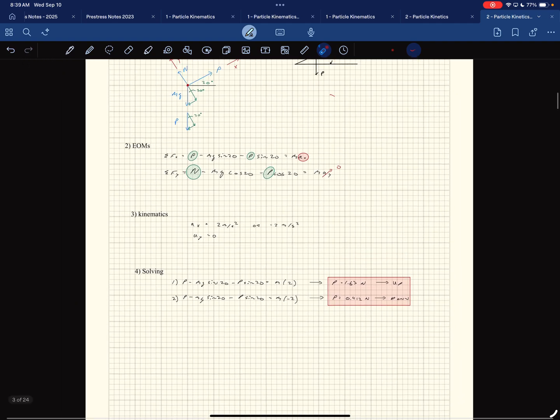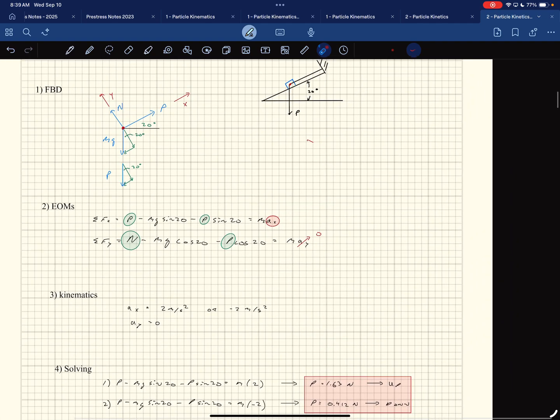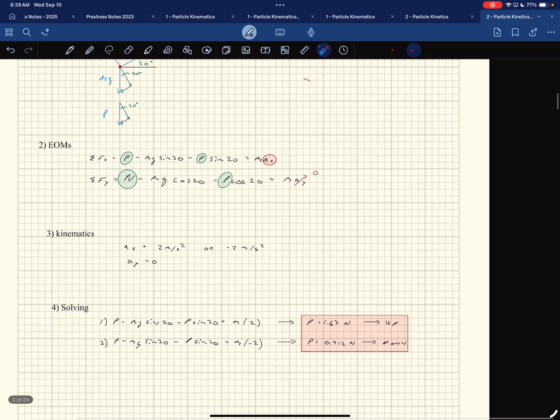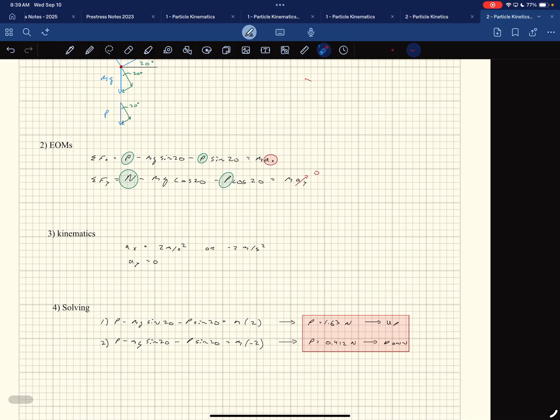The other thing to be really careful of, and I warned you from the get-go, is units. I'm really loose with this. I've done this long enough, and I find units so boring, but they are still very important. Everything goes in kilograms, newtons, and meters, and if you do that, everything works out. If you get given something in kilonewtons, make sure you turn it to newtons when you go in.